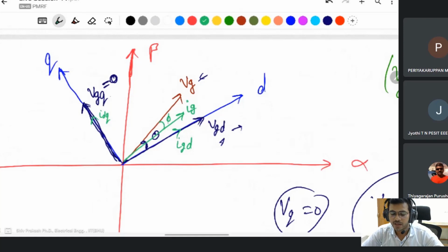There is a phi, the power factor angle difference between the voltage and current of a grid system. If the Q axis of the VG is 0, and if the current is also made 0 at the Q axis, then all of the current magnitude is the same as the D axis magnitude, IGD.